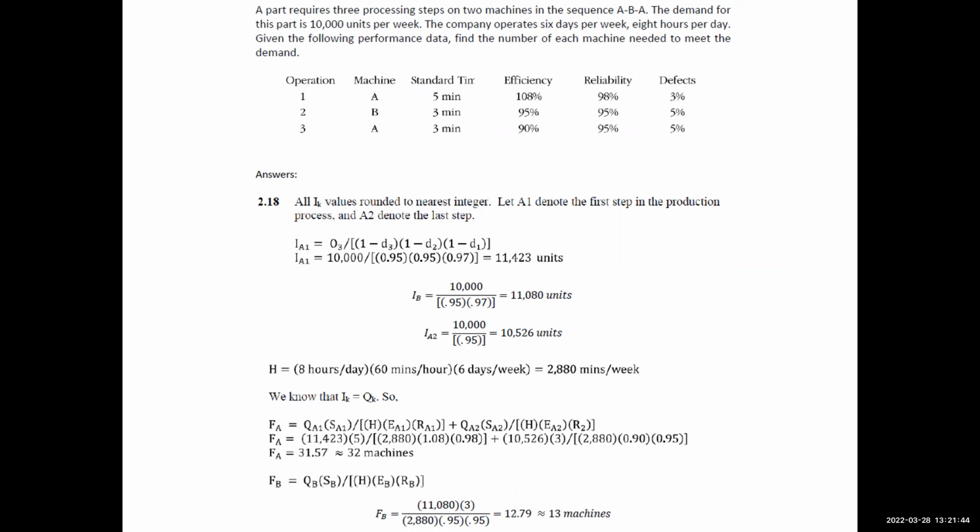In this case, we have the standard time, the processing time per machine, in minutes. So the time for processing also has to have a unit in minutes, so you can cancel them out. I think that will be the major challenge. Make sure that you use the right time units when computing this information, so everything can cancel out and you get the right number.